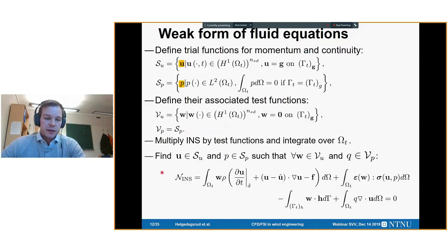But the Navier-Stokes will take this form now in the weak form, which means that it has changed to an error minimalization problem. So you satisfy the Navier-Stokes equations inside an element rather than in every point in space. So this is the point of departure for numerical implementation and discretization. We collect these terms into an operator that kind of solves the Navier-Stokes.